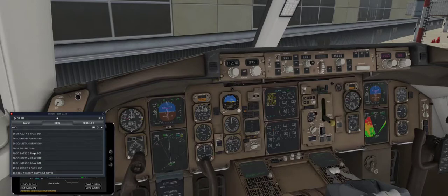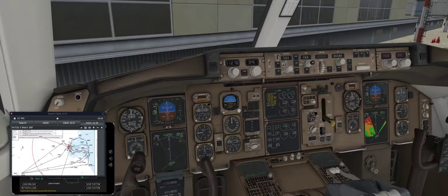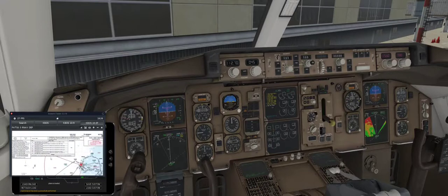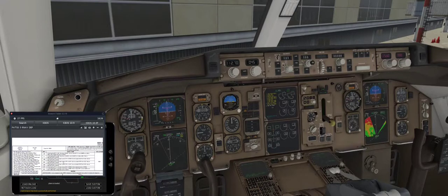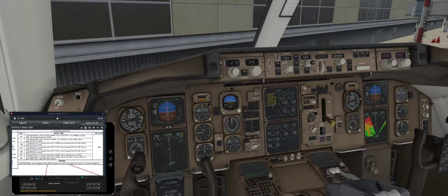And the PATS 5 departure is usually the best to take coming from Boston towards south of Boston and towards the east, which obviously is the direction we're going. And you really should review these and be familiar. It's basically saying if you're coming from 15 right, here's what you do. Climb to heading 150, intercept this course to Fox. Do not exceed 210 knots until 520.